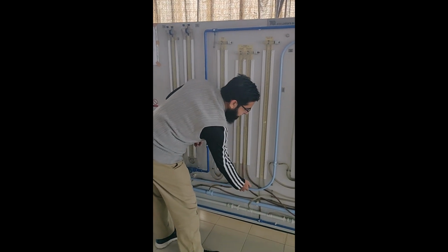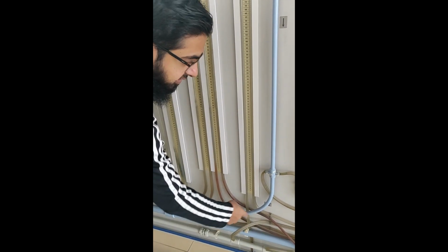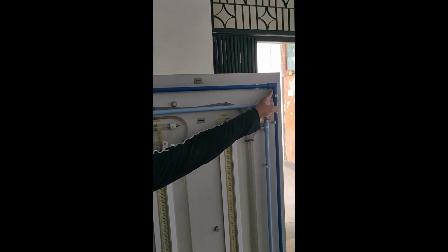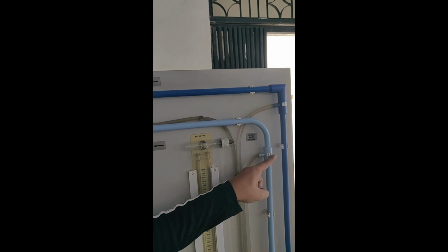Earlier we talked about losses due to sudden expansion and contraction. In the same way, there could be losses if there are different kinds of fittings, for example valves, taps, anything like that. And also there are losses whenever we have bends. For example, this is a pipe system and you would see a bend here. Now this kind of bend is known as an easy bend, as opposed to another type of bend which is known as a sharp bend. This is a 90-degree sharp bend and this is a 90-degree easy bend.